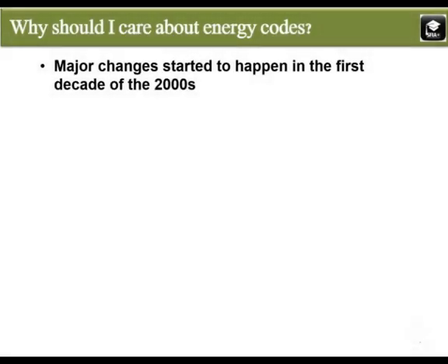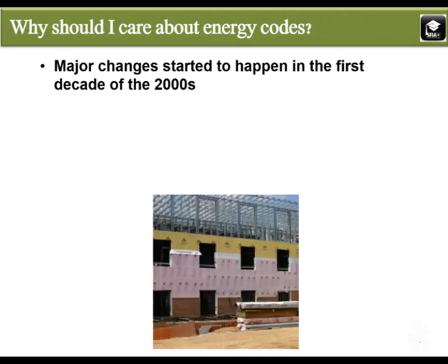In addition to the increased adoption and enforcement, a few other reasons began to impact why energy codes affect cold-formed steel construction. Probably the most significant issue is the impact of continuous insulation, which is now required in almost all buildings. Continuous insulation is typically installed on the exterior of stud walls in the form of a foam board similar to that shown in pink in this picture. It was non-existent in early energy codes for framed construction, but became a standard requirement as the focus of energy requirements turned towards reducing the thermal bridges across framing members.